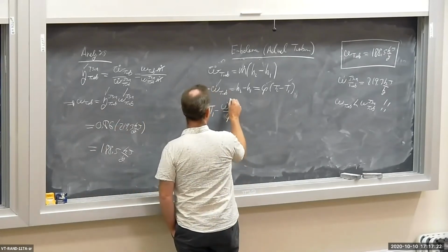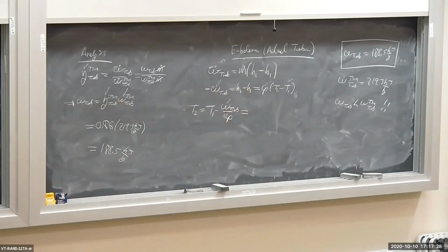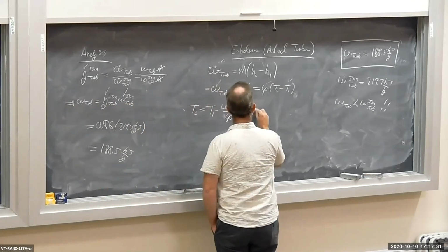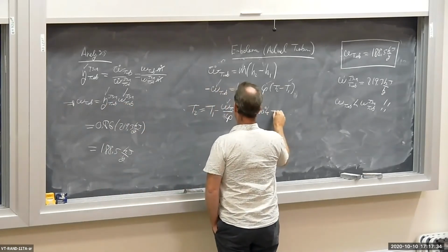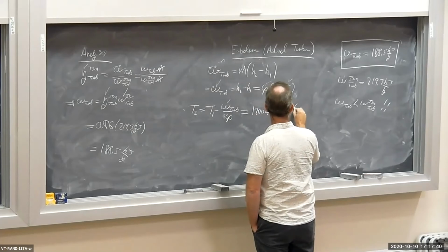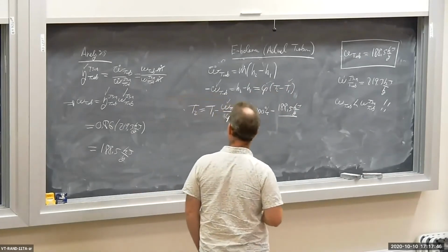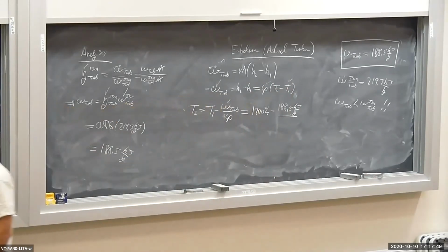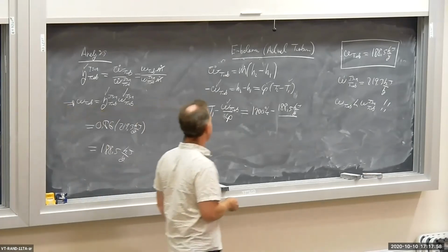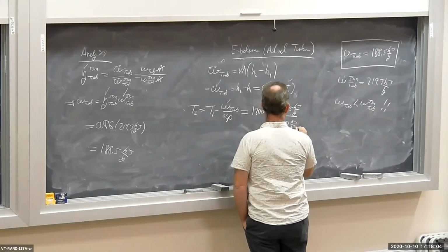All right, now I have W dot turbine, I have CP, and I have T1. Let's plug in. T1 is 1200 degrees Kelvin, minus W turbine, 188.5 kilojoules per kilogram. CP, we already looked CP up. What was CP? I guess I erased it. That was 1.142 kilojoules per kilogram degree Kelvin.